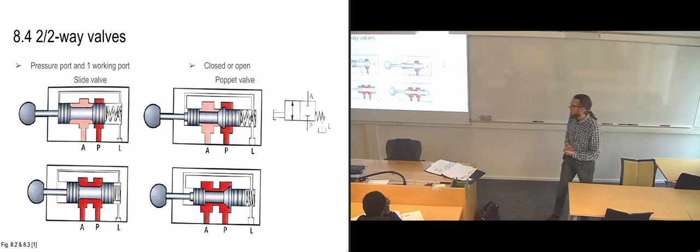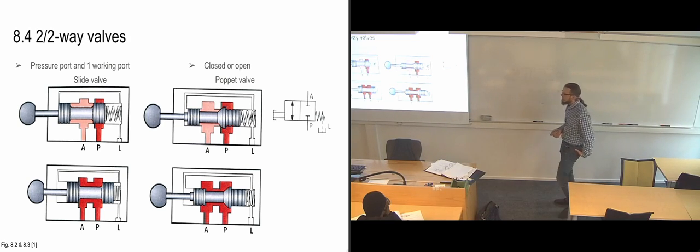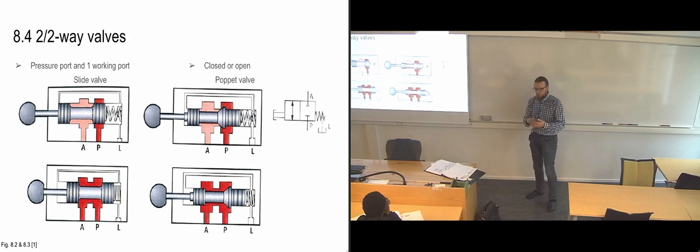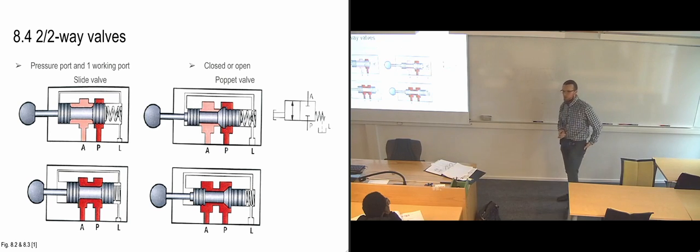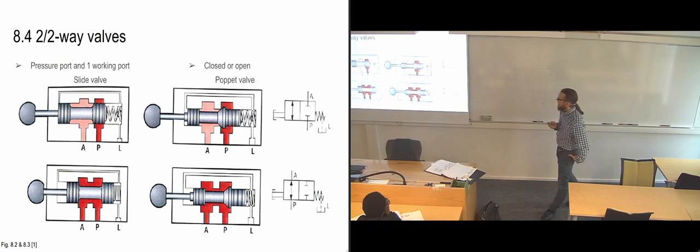You're not pushing the piston all the way to the end. Exactly why they have it on the Poppet one and not on the pressure port, I'm guessing the Poppet one has been designed to close completely without leakage, and to close very quickly. So they want to avoid trapping leakage oil on that side, giving it a chance to go all the way to the end. And then when it's activated, you get full pressure through.